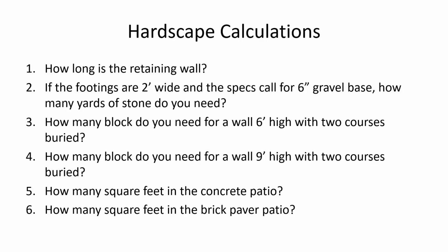But here are your hardscape calculations. How long is the retaining wall? That's question number 1. So measure it with your quarter scale. Number 2, if the footings are 2 foot wide and the specs call for a 6-inch gravel base, how many yards of stone do you need?